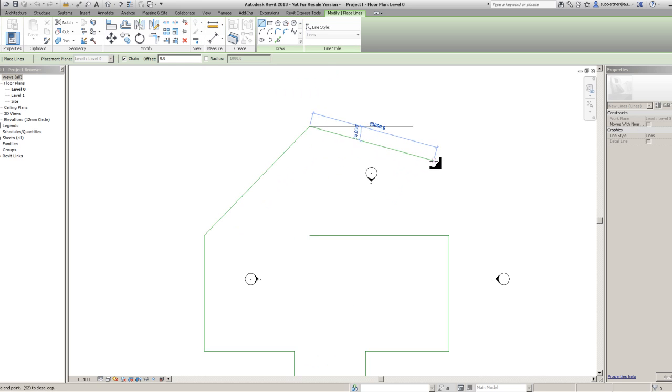There we go. Now, just moving my mouse around here, we've got our standard CAD snaps, our object snaps. They're the same symbols as they are in AutoCAD as well. We've got our midpoints, we've got endpoints, we've got lots of others, okay? Now, I'm just going to click on the endpoint of this line. Or what we also have, if we look down here at the bottom of my screen, we can see it says SZ to close loop.